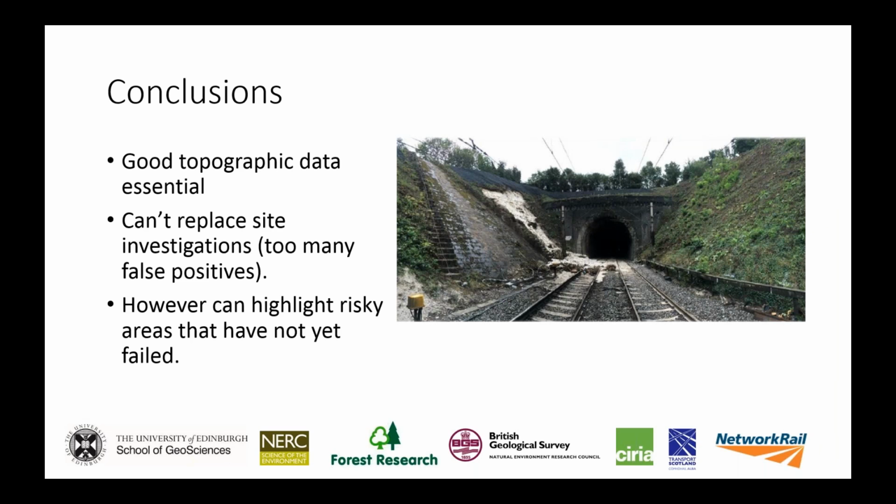So that brings me to my conclusion slide. The main thing that we found from this study is that we can spend a lot of time writing software, but the predictions are really only as good as the topographic data that underlies our analysis. Right now, we do have LiDAR for bits of the UK from the Environment Agency and the Scottish Government. Those high-resolution topographic datasets tend to be associated with flooding, so they stay in the river valleys, but that's not really of much use for landslide studies. What we really need is LiDAR that goes up onto the hill slopes.